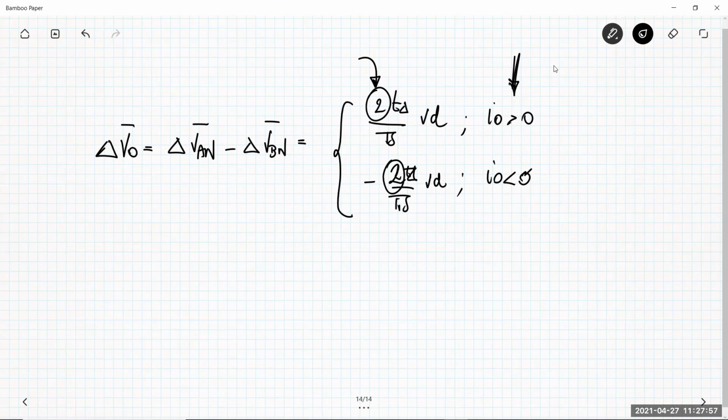Antonio Molas asks, which are the reasons to use unipolar or bipolar pulse width modulation? Basically, the reasons are in the output spectrum that I can use. This is one of the main reasons, because one of the main differences, maybe the most important one, is that you can reduce the harmonic content at the output for the unipolar one.